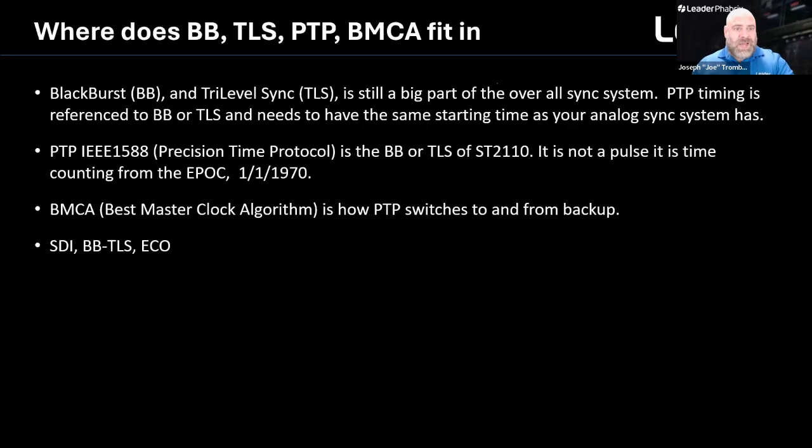So where do Blackburst and tri-level sync, PTP, and the BMCA all fit in? Blackburst and tri-level sync remain important on the SDI side, while PTP becomes the timing basis for ST 2110. PTP is not a pulse reference, it's a time-based system derived from epoch, and BMCA is the mechanism that determines takeover between the timing leaders. This matters because many facilities think in terms of genlock pulses, but IP timing requires thinking in terms of time distribution, announce messages, clock quality, and endpoint behavior during leader changes.